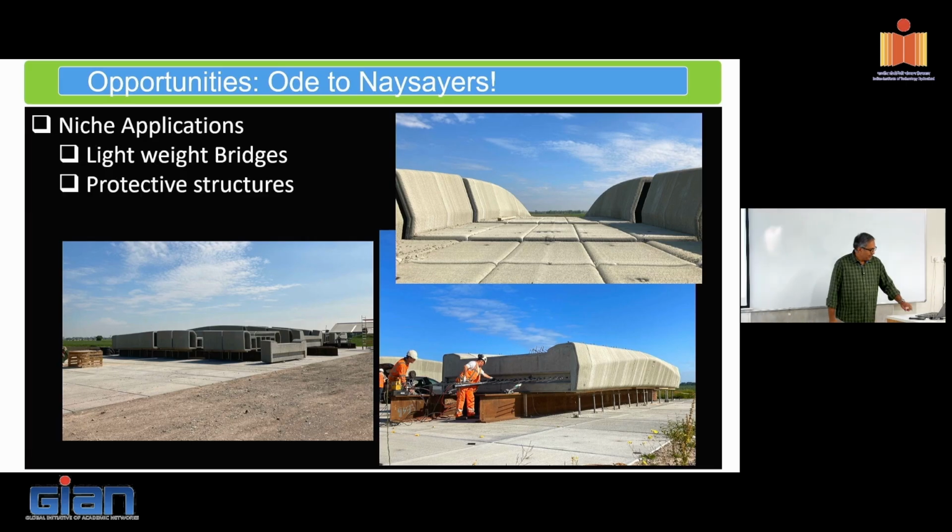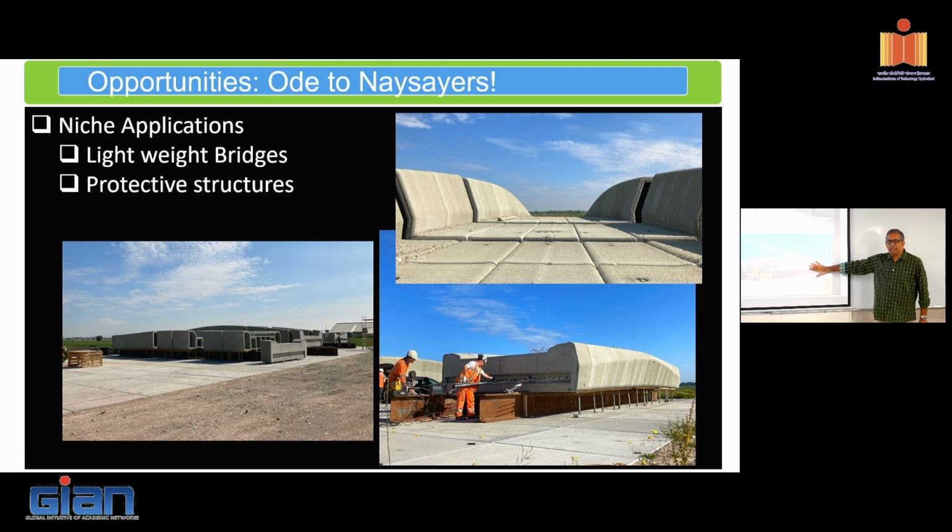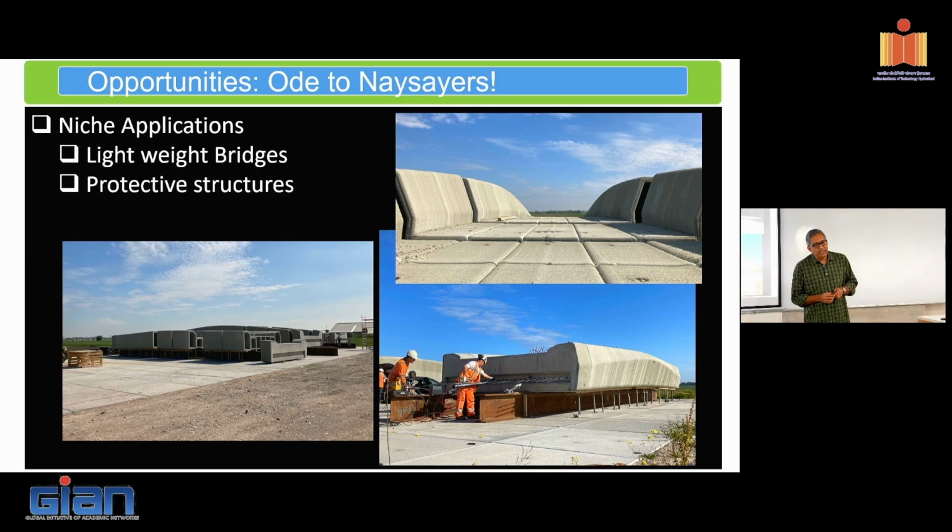So what you have to be clever about in this whole system is figuring out a way to embed the structural system inside. Whether you can take advantage of the printed form itself as a structural element, if you have enough confidence to do that. At this point, with available knowledge, we are not yet very comfortable with using this completely as a structural system. So what are we doing? We're basically resorting to redundancy, where we put a structural system inside the printed form and say that is going to take the force, unless you come up with a compression-only system like this.